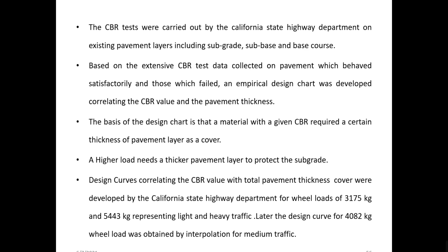They are trying to restrict the load to the standard axle load of 8 tons. So they are trying to restrict the load to 8 tons, which means the pavement thickness could be constant. Okay, it may not be continuously increasing, nor might it be decreasing. So hence the major importance of this pavement is to protect the subgrade soil.